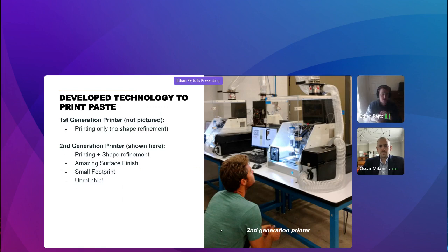We were doing this around the same time that some of these other MIM extrusion companies like Markforged and Desktop Metal were coming out with their systems. But we didn't really see a huge fit for that, because the parts were relatively rough. They had some porosity in them. The tolerances were relatively poor. So we were thinking, okay, we can do this, but this isn't good enough. What can we do to make this better so it actually fits an actual application?